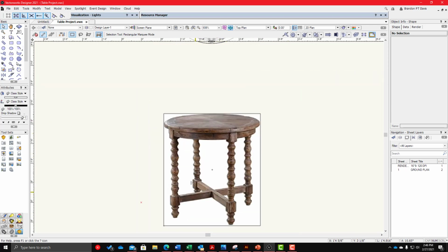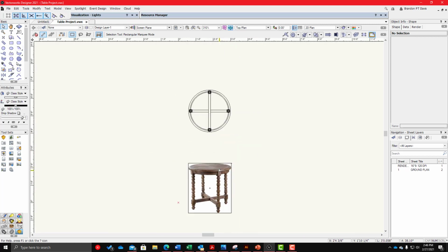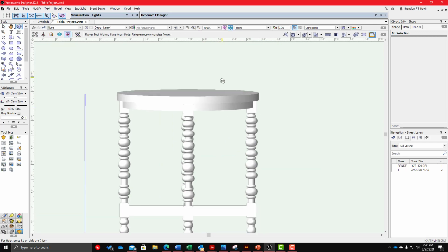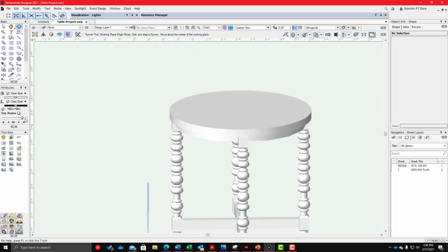So I think the last thing that I want to do is a fillet, probably 3/4 inch on the top. So I'm going to rotate this, go into our toolbox, get our 3D fillet. I'm going to make that 3/4 inch. It's only on the top.